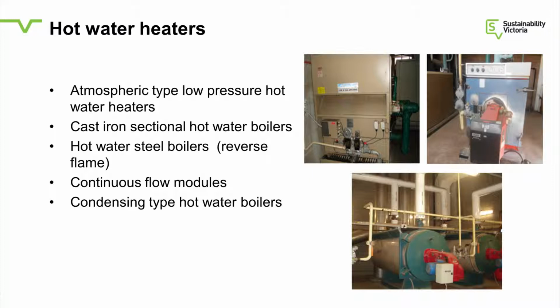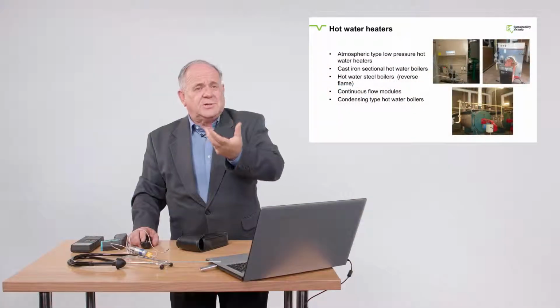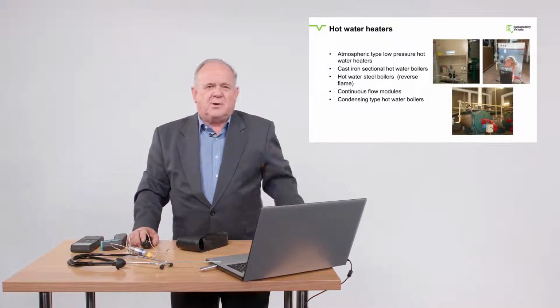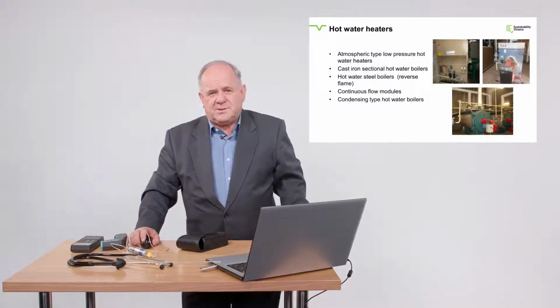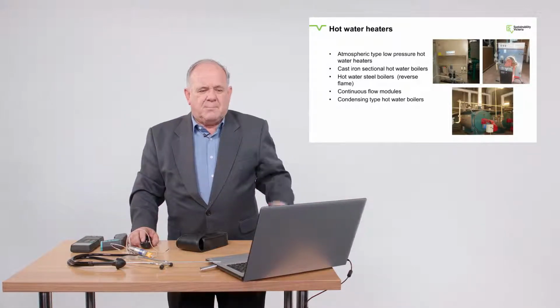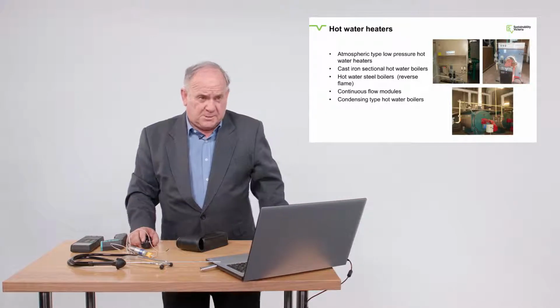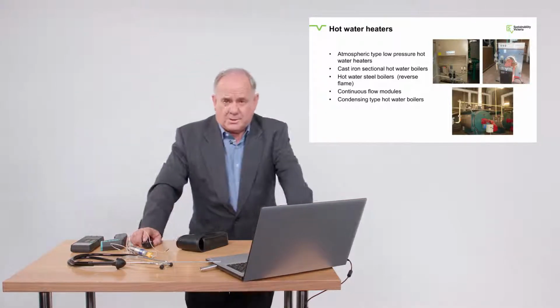All of these boilers are relatively efficient, but there's a trend now to make them even more efficient. So most new hospitals and things will have what's called condensing boilers. So you know how I said all that waste heat was going up the flue? They're actually recovering virtually all of that. So some of these can be operationally about 90 or greater than 90% efficient. And because of star ratings in buildings and things, most people are putting condensing boilers in these days in the hot water space.